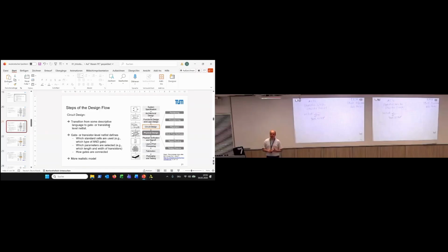Standard cell library means if you want to implement a NAND gate in a specific technology, someone, usually some analog mixed signal designer, has to sit down and define a NAND gate in this technology, with these transistors at that position, with connections in that layer of your metal stack, and so on. That is what you have to define to have a reasonable gate at the end.